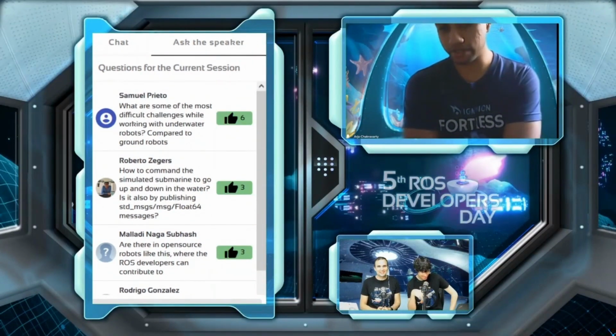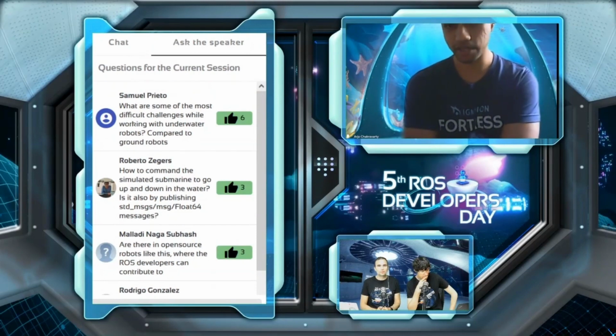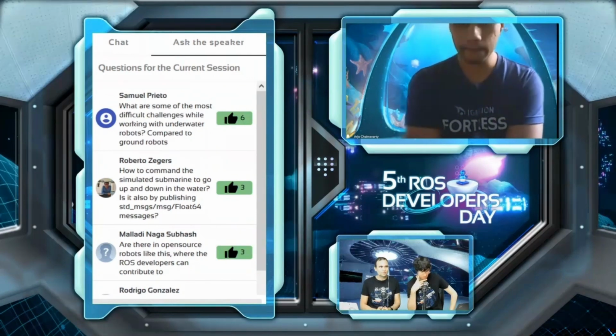Your best bet is either using a wire, or very low bit rate acoustic modems, and we do have Gazebo simulations for that also. They run at about 1,000 bits per second at most, with very high latency. So communications go through sound, basically. Either you use sound or you use a wire right now, so you don't really have too many options with communications.